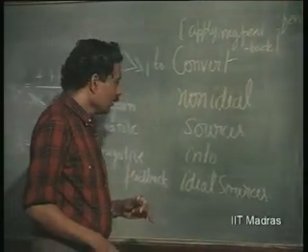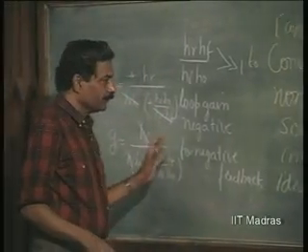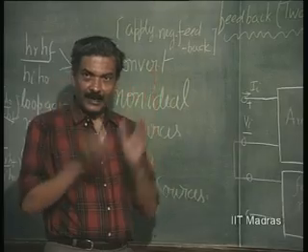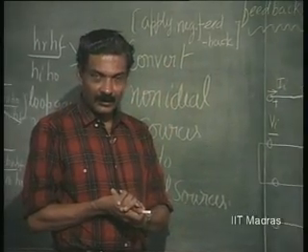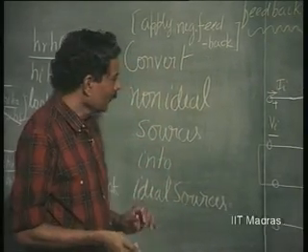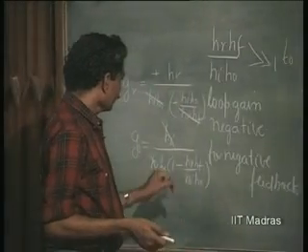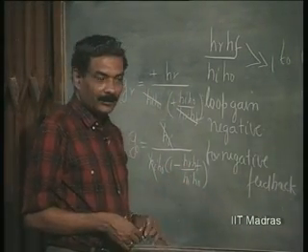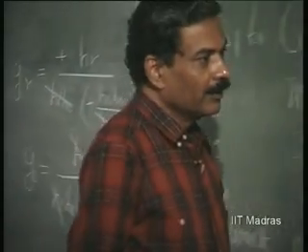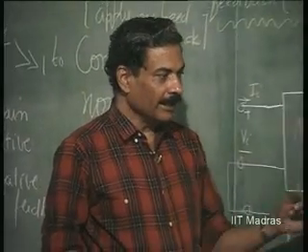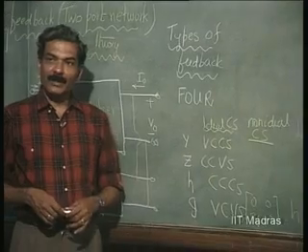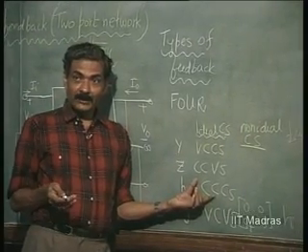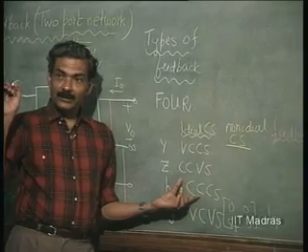So, this is the story of every negative feedback structure. First of all, how do we recognize whether it is negative feedback or not? The loop gain should be negative, that is what we established earlier also. In this particular case, the loop gain corresponds to HR HF divided by HI into H naught, that should be negative. Now, if I want an ideal current controlled current source, what kind of feedback should I give? It is current controlled, that means it should go towards short circuit.